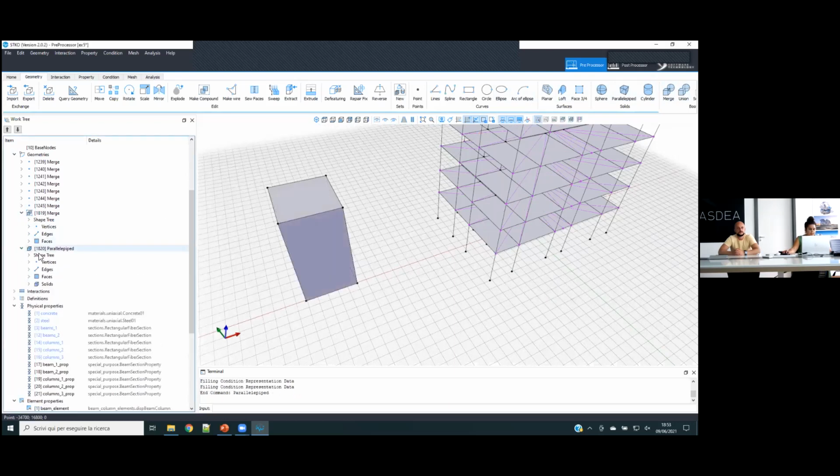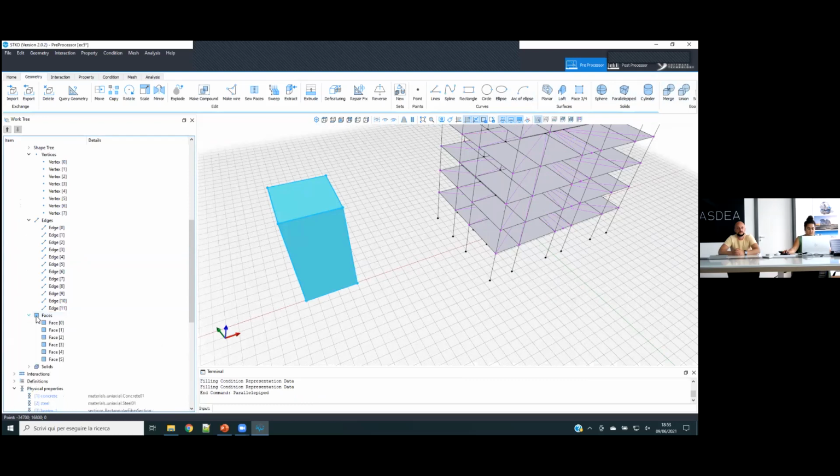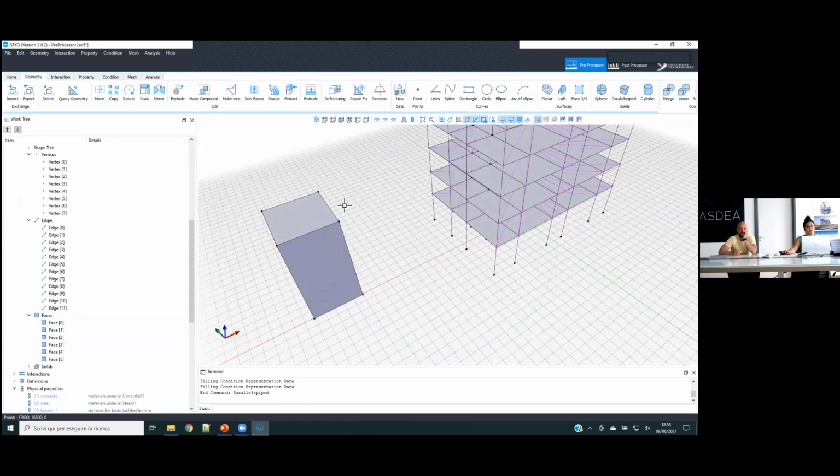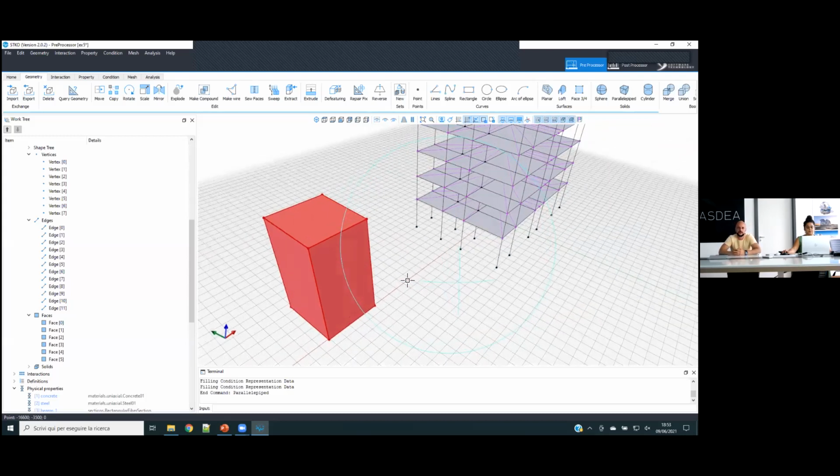This parallelepiped is enclosed inside a single geometry. It has vertices, edges, and faces. But I cannot really just take one of these nodes and move it around. Because that kind of operation will change the underlying geometry. For example, the cube is made of 6 planar faces, but if you move just one node, they will change to NURBS surfaces, because they will not be lying in the same plane. So it's not something that you can do.